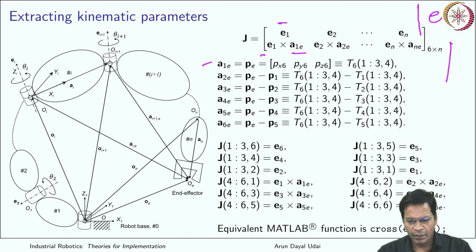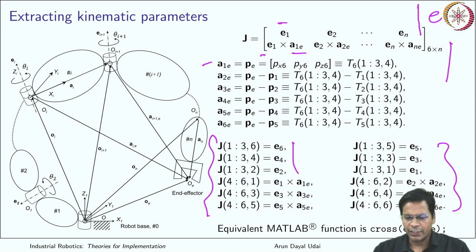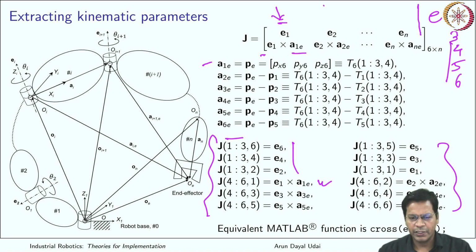So you have simply put those values into this matrix. These are just element to element transfers using the cross product. So the cross product result will go to the elements in rows 4, 5, 6. In rows 1, 2, 3, this will go. Got it? And for all the degrees of freedom it will come like this.